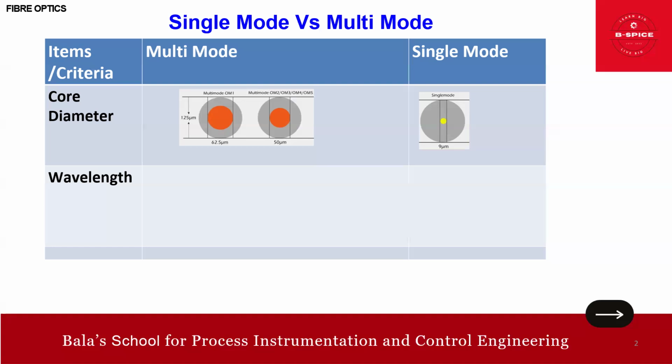One more terminology, bandwidth, we in fact covered earlier. Again, I repeat, it's the amount of data transmitted. You should not confuse bandwidth and attenuation. So coming back to the subject, the core of single mode is small, typically 9 micrometer. It has a lower attenuation, supporting higher bandwidth and longer transmission distance.